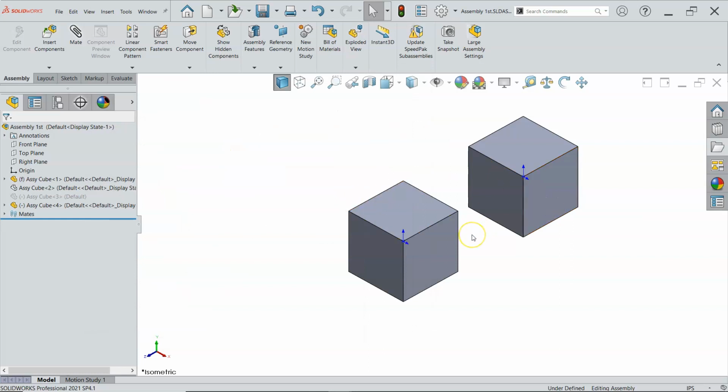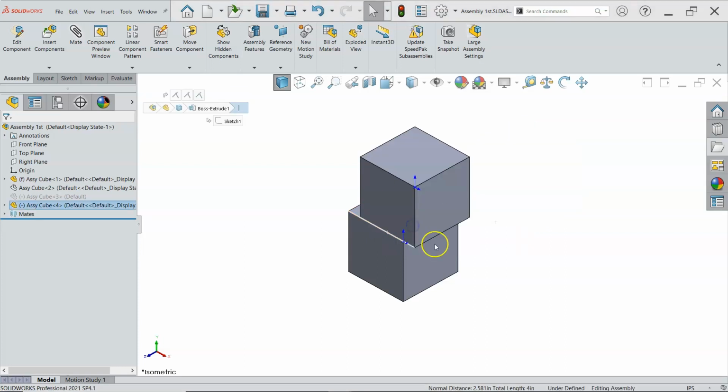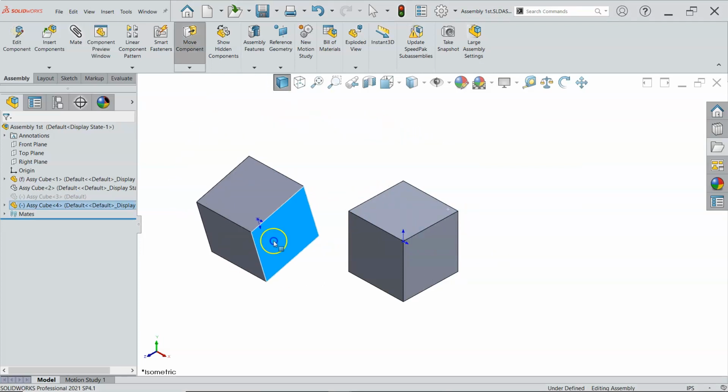All right, so we've done coincident, just that first location. A lot of things are going to be coincident. We've done the face-to-face. We've done the planar. We can also do edges, but in our hierarchy, planes and faces are going to be first choice. Edges, if I select an edge, hold down the control button, select another edge, and make that coincident, they're going to align, but now I also have rotation.